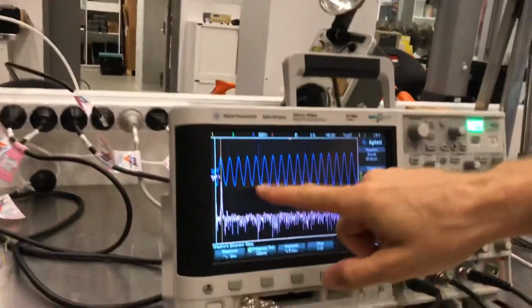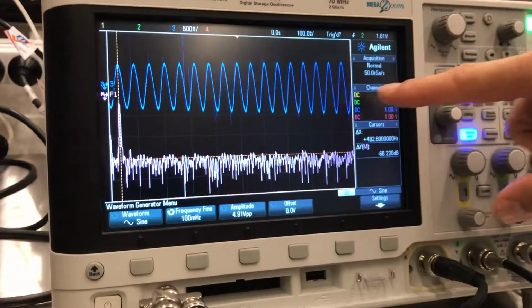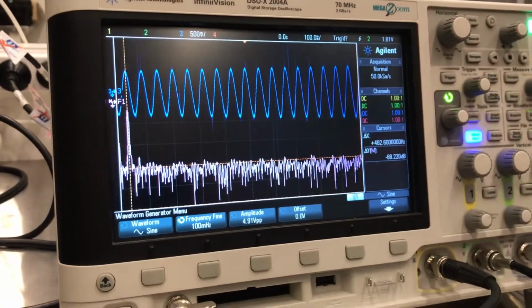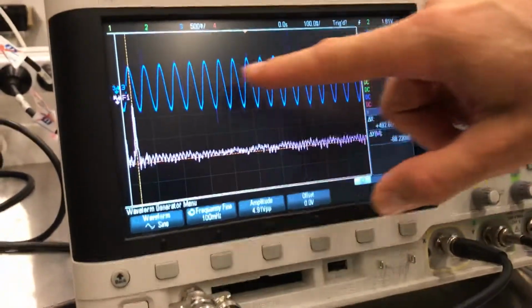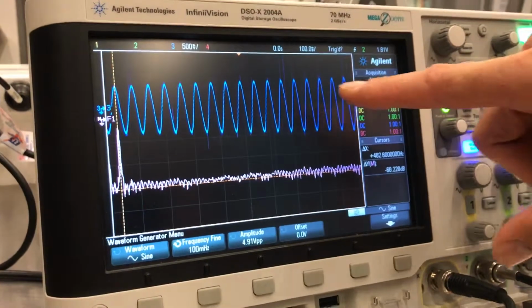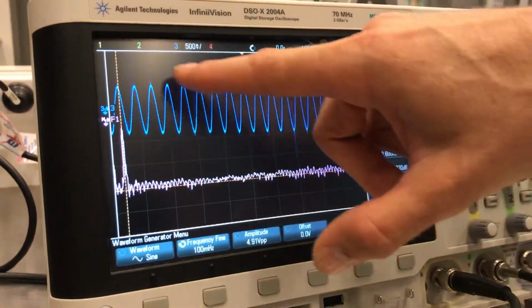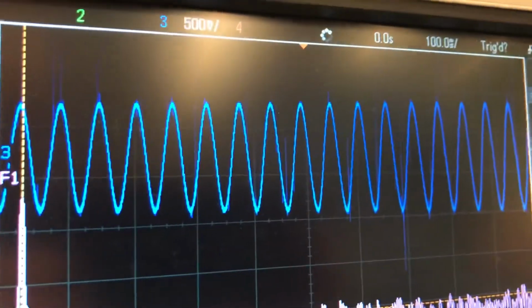If we look at the oscilloscope, we're making a measurement immediately of the vibration of the beam as is expected. The blue trace being a time signal that the vibrometer output gives us, and we can see it steadily increasing as we start from the root of the beam up towards the tip of the beam. You can also see some signal level dropouts in this signal here as a result of the speckle noise that was mentioned in a previous video.